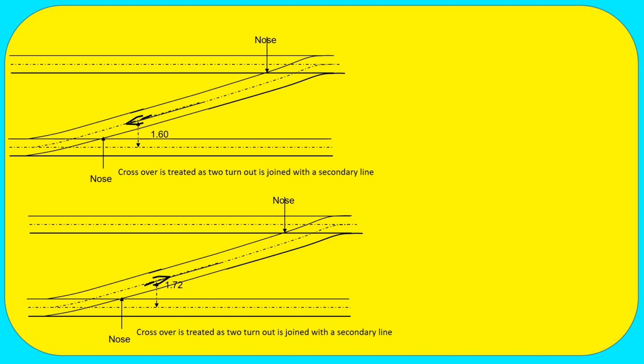But if you keep the section insulator in 0 stagger, then you can reduce it. You have to calculate. I will show you the calculation, how far you can keep it. You can reduce the stagger here.